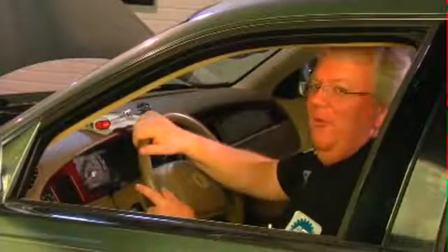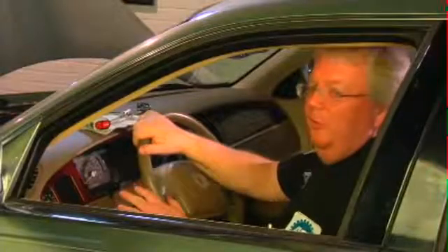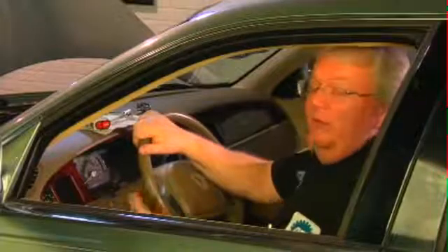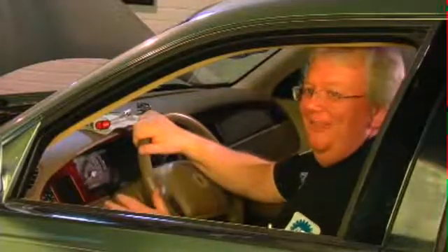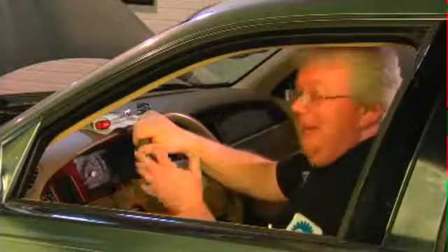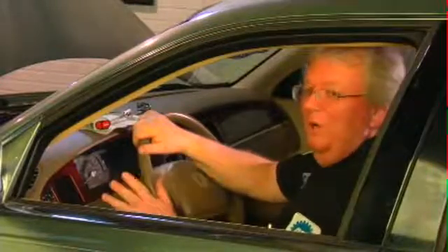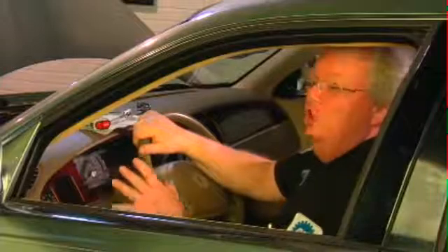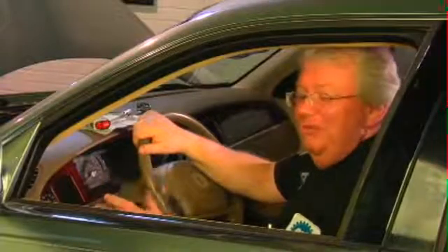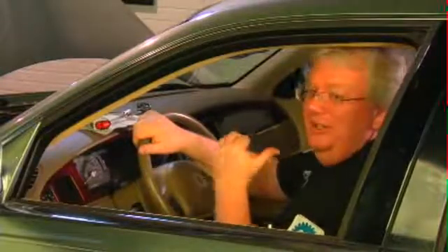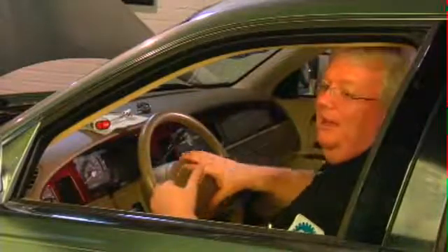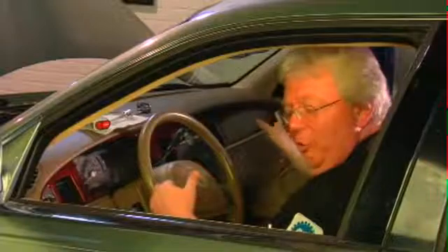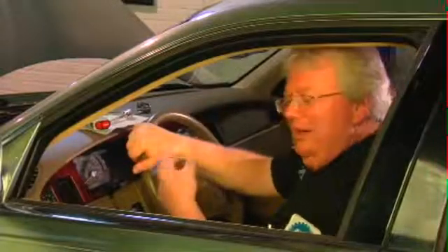Well, one of the first things we have to do when we work on steering columns, whether we're just fixing the tilt wheel or removing the column and replacing the column, is we have to make the airbags safe. So most vehicles since the late 80s into the 90s have standard equipment airbags, and may have numerous airbags on the vehicle: side curtains, side airbags in the seat or the B-pillars, and of course the driver steering column mounted and frontal passenger airbags. So how do you make them safe?